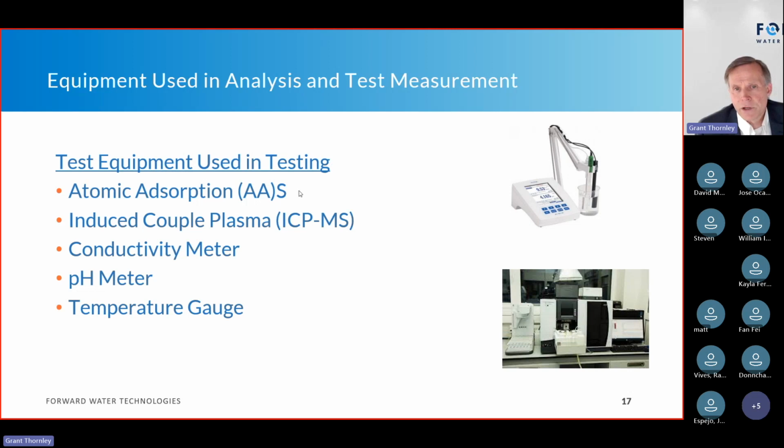A lot of people use atomic absorption when they do the fixed column because it's very inexpensive to do. So you have a lot of samples, whereas a lot of people do not have an ICP, inductively coupled plasma. They've got to send that out, anywhere from $100 to $200 a sample. So typically they do absorption. It's a good instrument, but when you get to a point that you really want to validate, send it out and spend the money on an ICP mass spec.